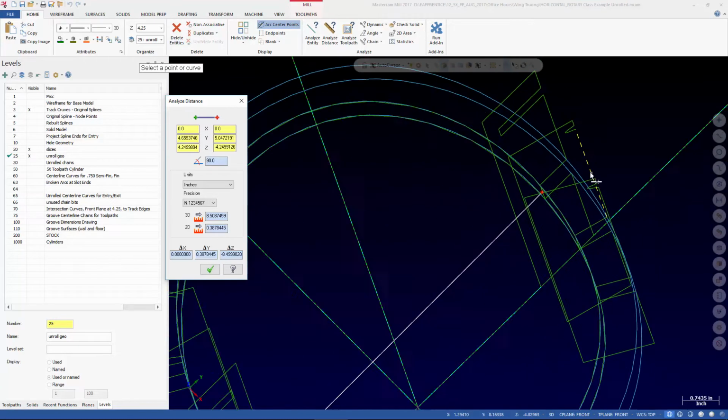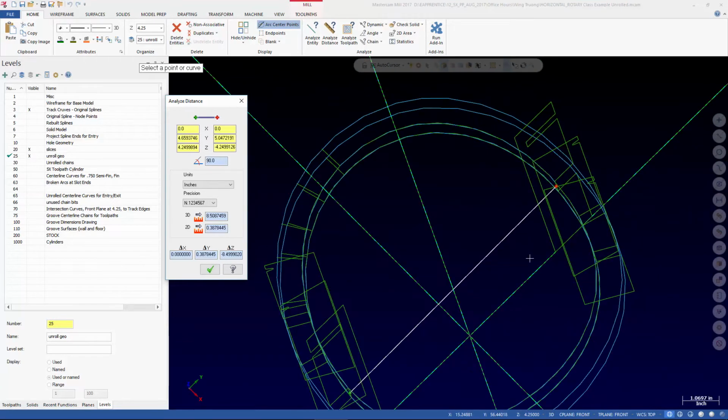Yeah, we could do analyze dynamic. We could click the solid face, and that would give us the radius. But the other thing that you'll see about this, when I started analyzing some of the geometry, is that this is modeled where things are just slightly off. So in a case like this, 8.499999, we can pretty safely assume that they meant to do it at 8.5.